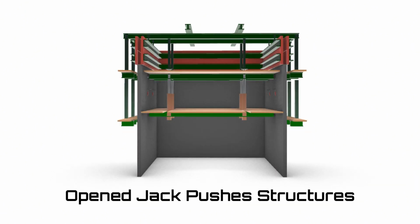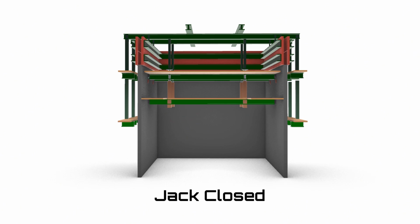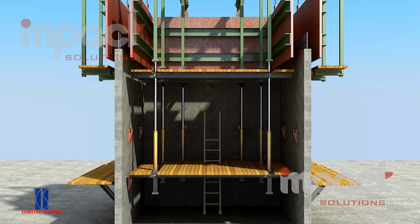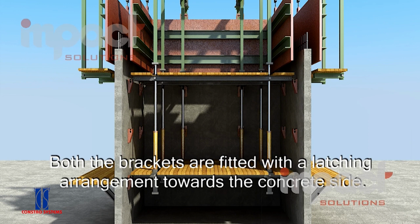These brackets are controlled by a strong hydraulic system and are used to lift the system to the next floor when work on each floor is completed. The hydraulic lifting system moves the bracket vertically with the formwork. When the hardening of concrete in the floor is complete, the hydraulic jack opens and pushes the structure upward.